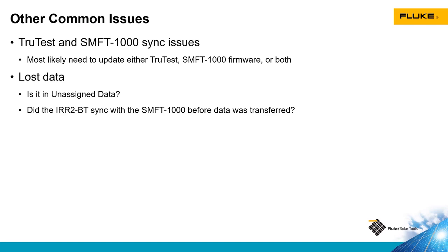An interesting thing about the SMFT1000 with the IRR2, once you connect the two, the IRR2 will start data logging. And when you connect the IRR2 to the SMFT1000, it will ask you if you want to synchronize the clocks by hitting the up button. Always do that.